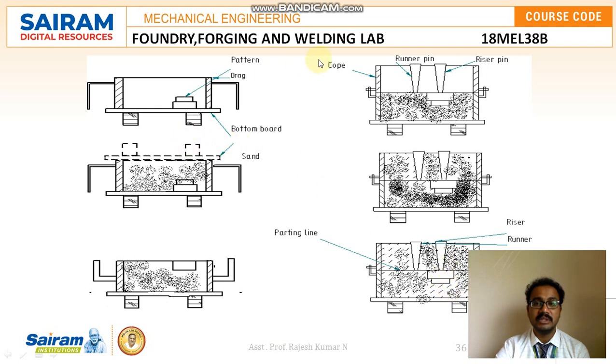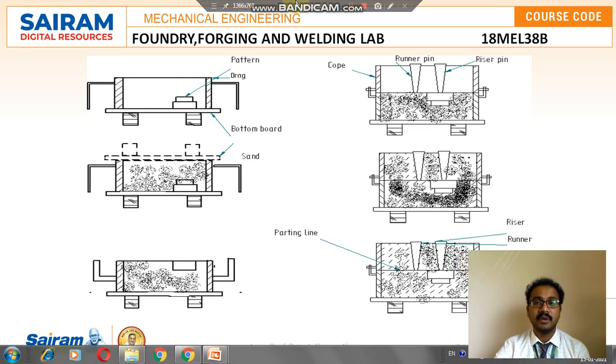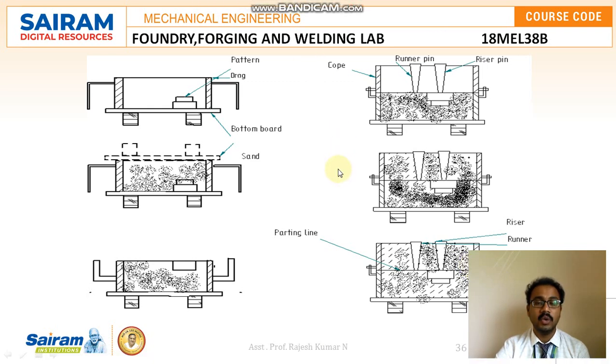Once the pattern is kept, I will be filling up with some sand till this particular layer, and later I will again go with this runner and riser pin with the help of a cope. I'll be filling up and creating the hole. It will be completely merged into this particular place, and once it is properly done, I'll be waiting for some more time, allowing the cooling process.